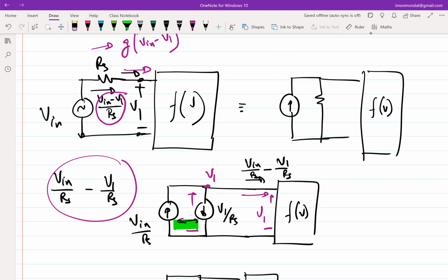Okay. Yes. So, sir, is it safe to say that in case of non-linearity, the principle of superposition is only true for linear circuits, right? Superposition is not true for nonlinear circuits, and essentially that is why wherever you are using superposition, you cannot have nonlinear circuits, right? But having said that, if I use a nonlinear element and I know how to linearize it in the incremental model, they are all linear.